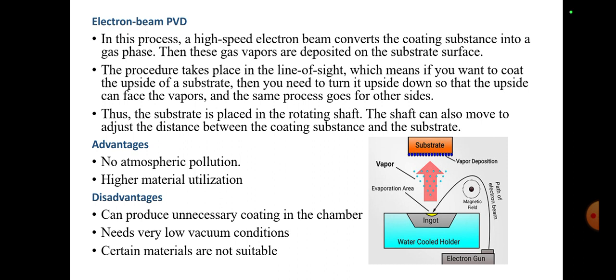The advantages are no atmospheric pollution and higher material utilization. The disadvantages are that it can produce unnecessary coatings in the chamber, needs very low vacuum conditions, and certain materials are not suitable.